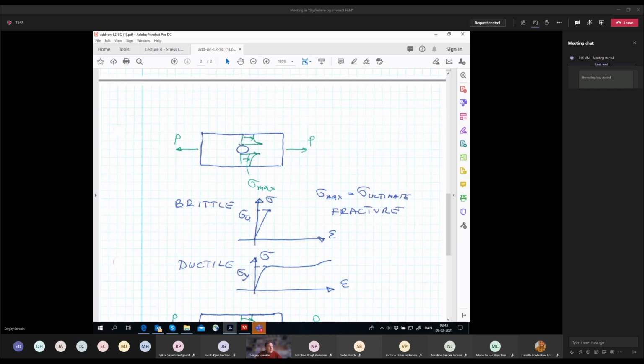So it means that the ultimate stress will immediately pierce through this thickness, and then you have instantaneous failure of this specimen, because as soon as you attain here this ultimate stress, you have an infinitely large stress concentration factor, and you have a fracture like this and fracture like this.